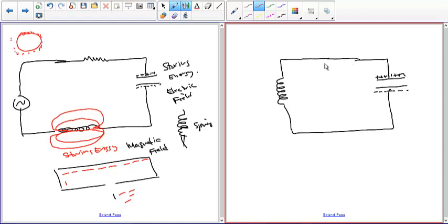So first it discharges, storing the energy in the magnetic field. So you're losing the energy in the electric field as you discharge the capacitor. But as you do that, you're creating a magnetic field within the coil. So you're not losing the energy, you're just taking the energy from the electric field into a magnetic field. And then as this is changing, that creates a current which then causes it to go all the way over here. Okay, so when you first close the switch, it discharges the capacitor, stores the energy in the magnetic field. Not immediately though, it'll do it depending on the circuit. And then